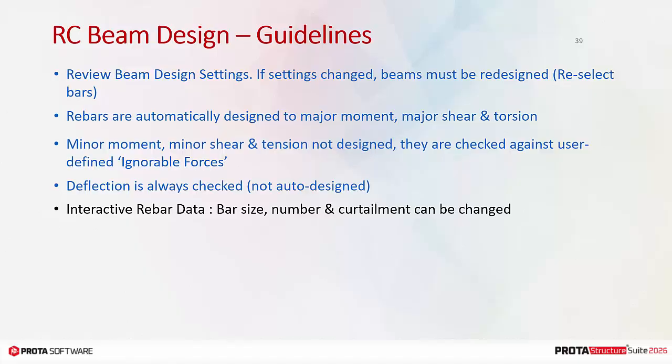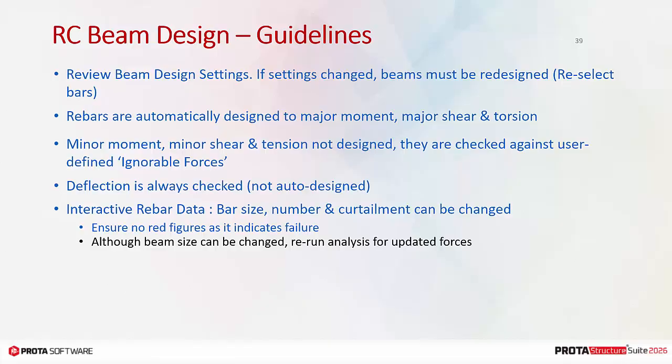In the interactive reinforcement design data, bar size, number and curtailment can be changed. Ensure no red figures as it indicates failure. Although beam size can be changed, rerun analysis for updated forces.